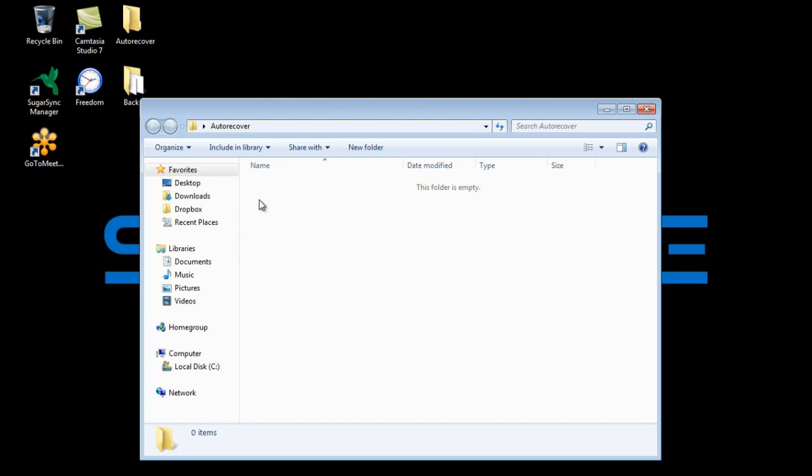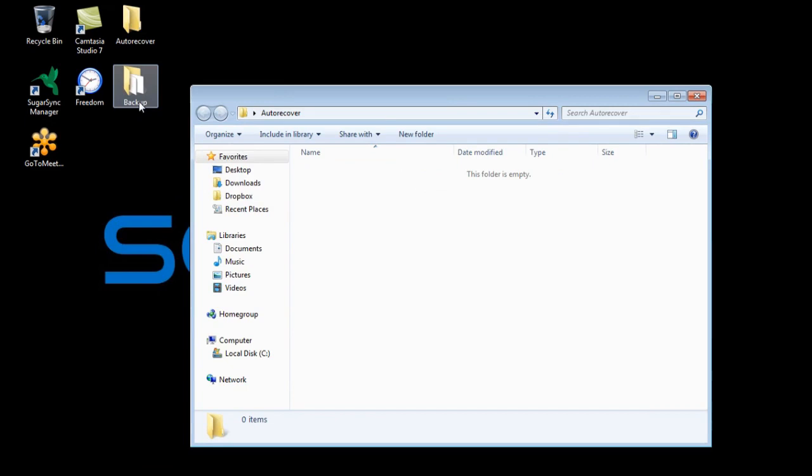For most people, I typically recommend, if you're not using a PDM system, to turn on the Autorecover and create a folder for Autorecover. And usually not worry about backup, as you tend to create quite a few backup files if you're working with a lot of parts. So typically Autorecover will be more helpful than that backup. But that's how you set up both of those.